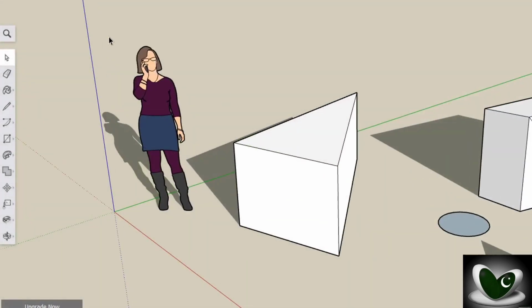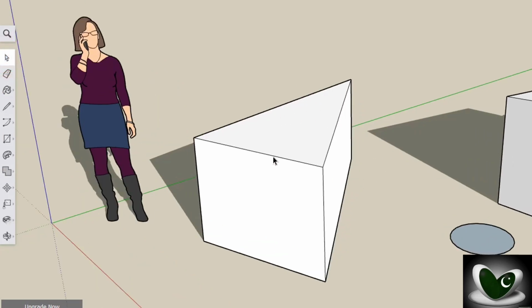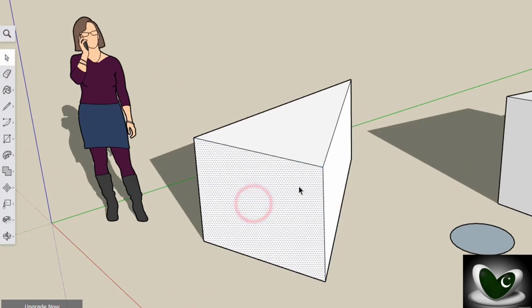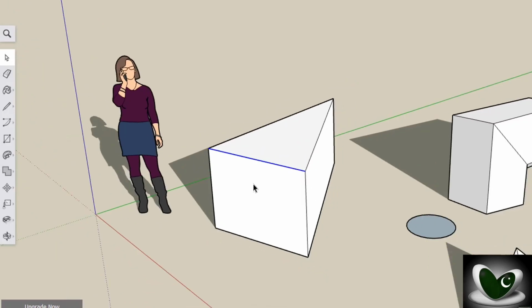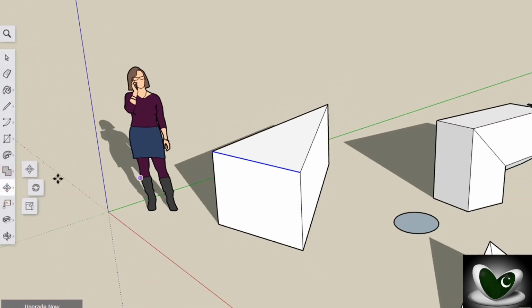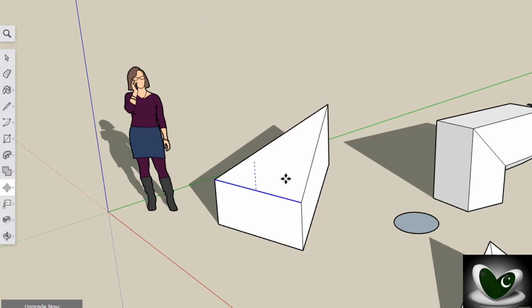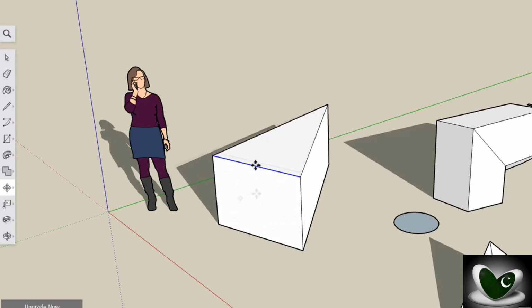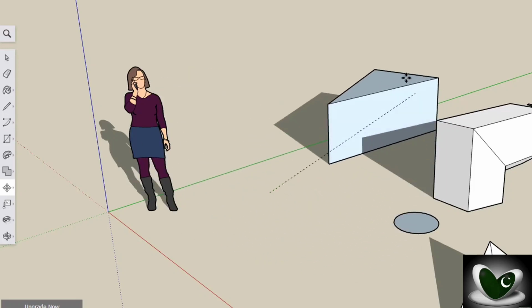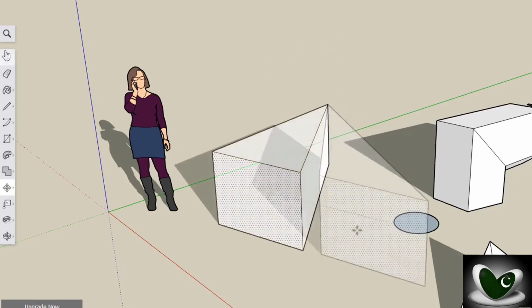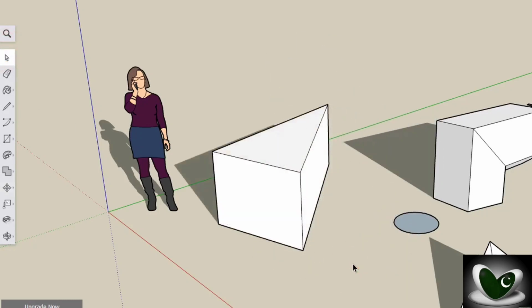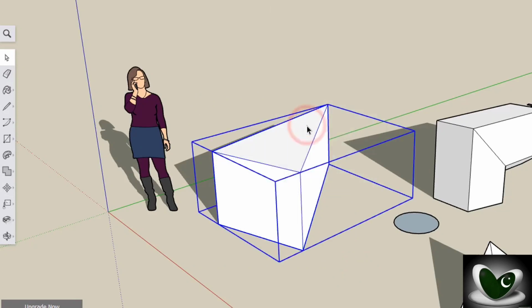Now let's see how to edit and reshape the objects on your workspace by using the tools on the left side. First of all, you have to use the Select tool to select the object to be edited by clicking on it. By default, SketchUp selects the subcomponents of an object, such as single sides or faces. So when you move or edit any 3D custom object you have made, this gets deformed as its subcomponents are moved or edited. To modify a 3D object entirely, you have to select all its subcomponents together. Right-click and go to Make Group.